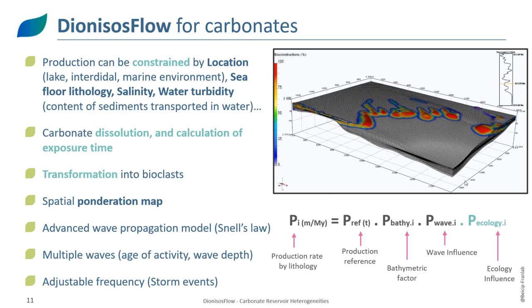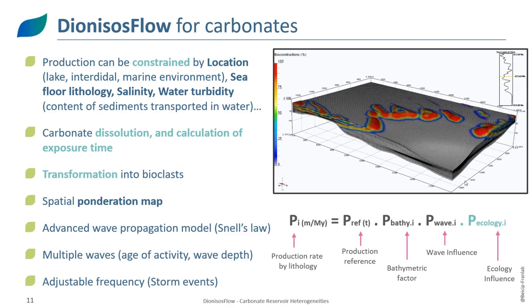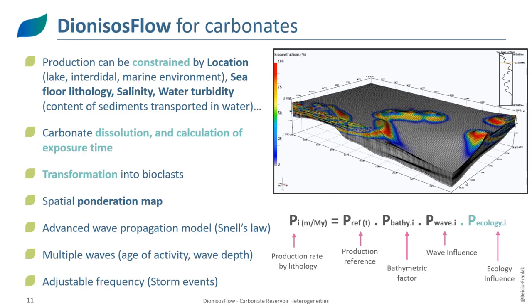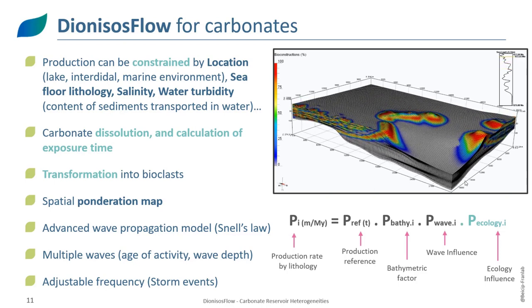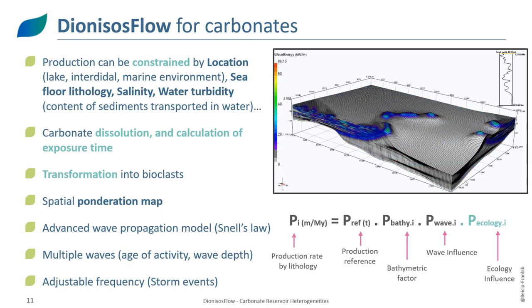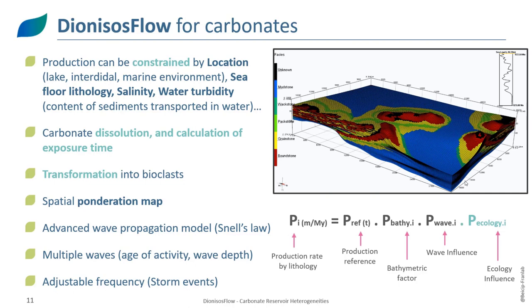Now to the right, you see a model running in time. You see to the right the sea level. Now you're looking at the bathymetry results. So here you see different kinds of bathymetry, and then you see the wave energy distribution, which is not, even though the wave is coming from this corner over here, you see that the wave energy is distributed not in a linear way, but it refracts based on the shape, based on the bathymetry and the coastline.